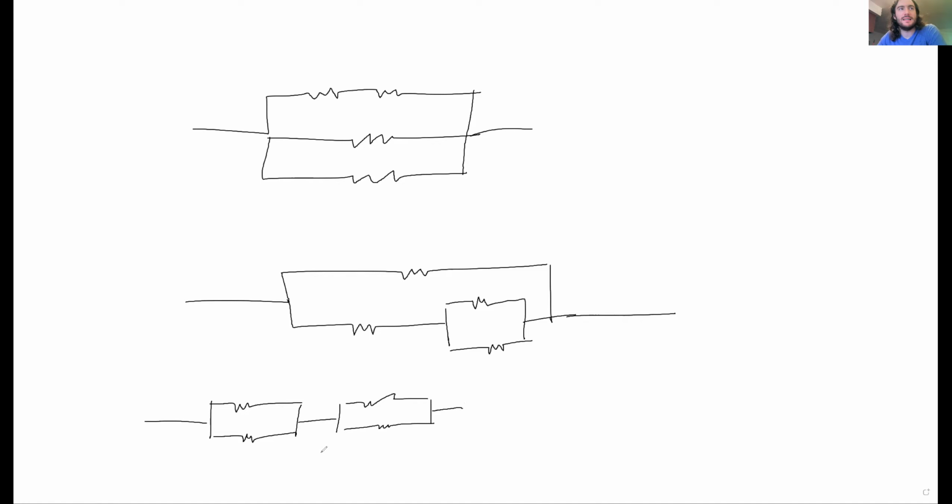And this happens to be identical to the following. So we count these as 2 combinations here. So this one and this one. Those, we count that as 2 combinations, but those are identical. So 2 in parallel in series with 2 in parallel is the same as 2 in series in parallel with 2 in series. Does this apply as a general rule, or is it only for this setup? It's not a general rule. It's only when all the R values are identical. I see. Okay.